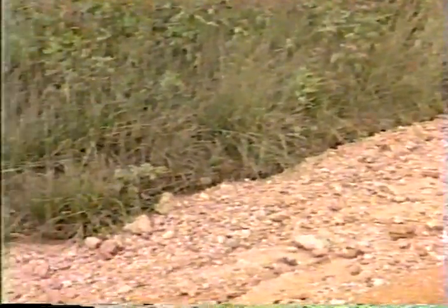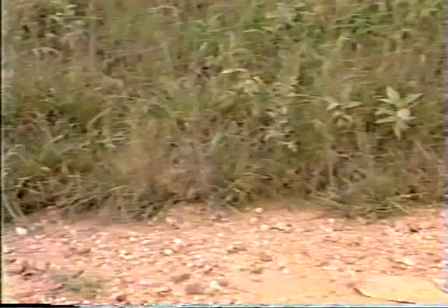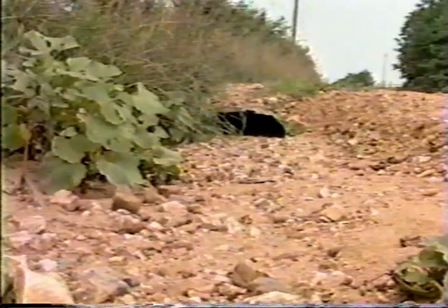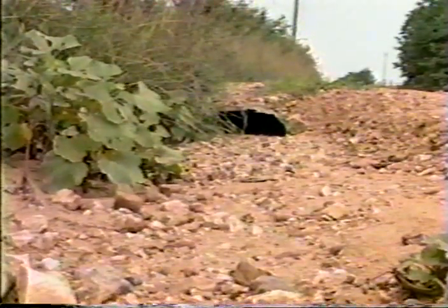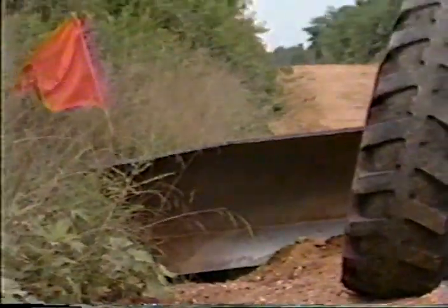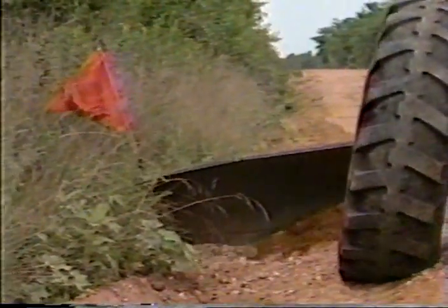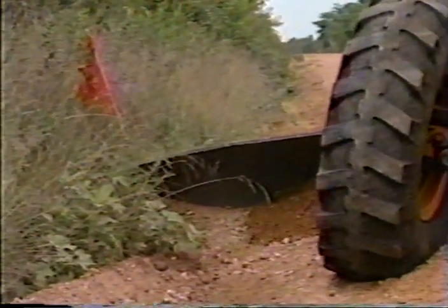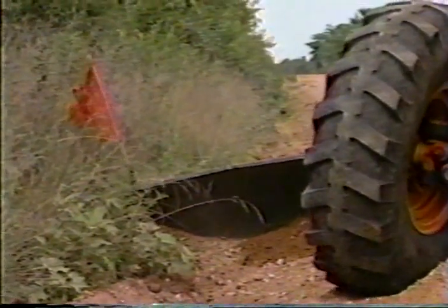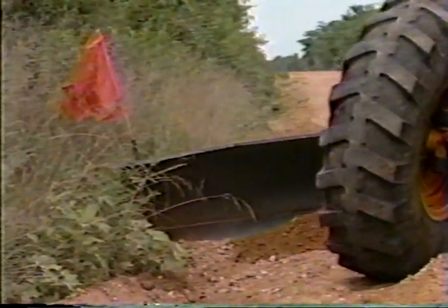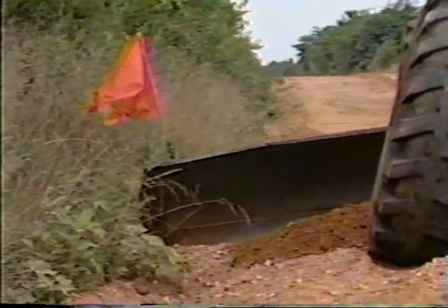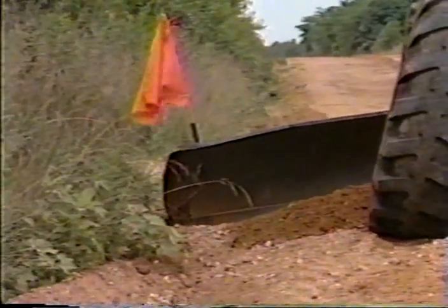Before beginning the smoothing operation, check the drainage conditions on the section of roadway about to be smoothed. Aggregate tends to wash into the ditches during heavy rains and must be removed for proper drainage. To remove aggregate from the existing ditch, swing the blade carriage over to the pull side as far as possible and angle the blade to approximately 45 degrees. The aggregate should be graded up onto the shoulder area into a windrow.